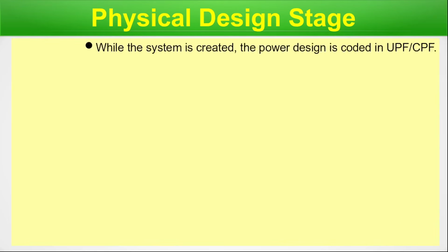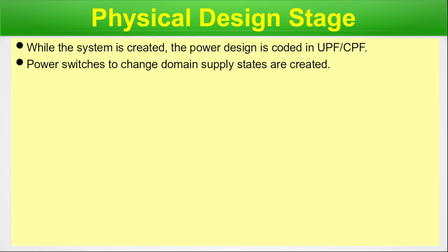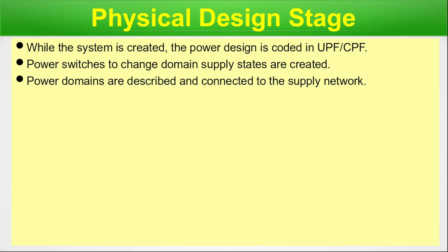Physical design stage. Here in this slide, we will talk about the implementation of the retention cell in the physical design part of the chip design. While the system is created, power design is coded in UPF or CPF. Power switches to change domain supply states are created. Power domains are described and connected to the supply network.